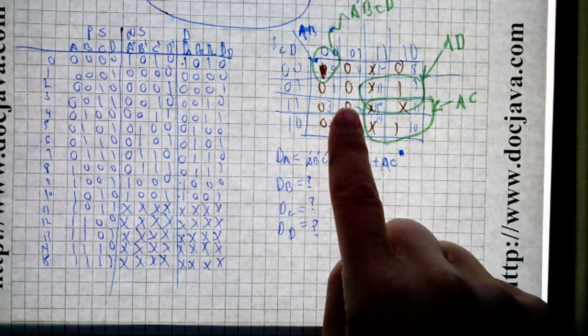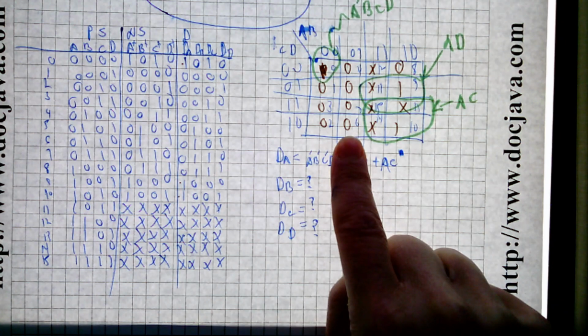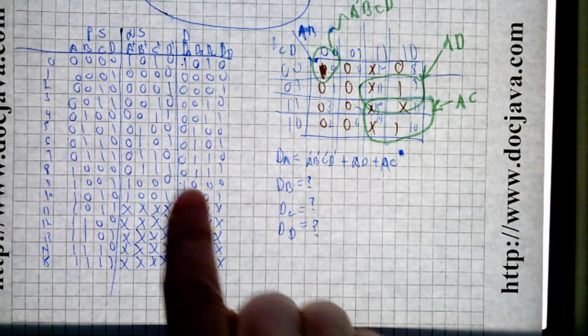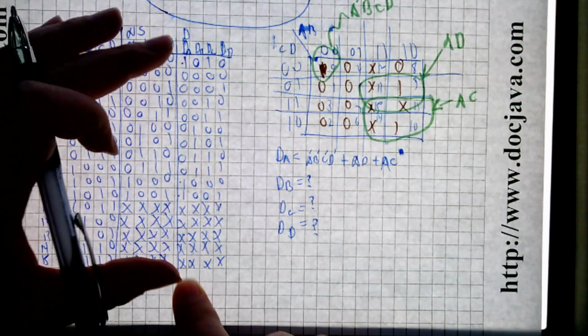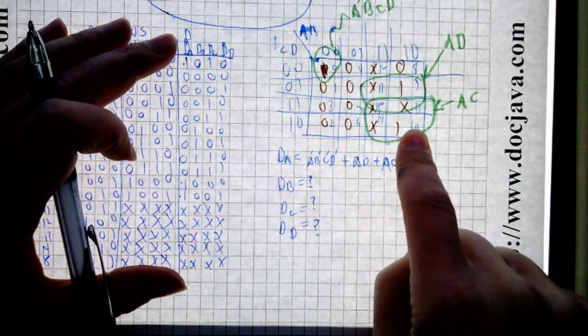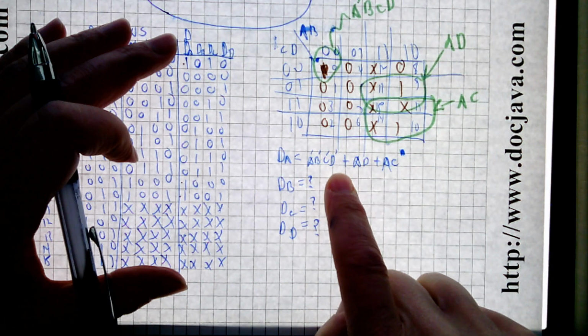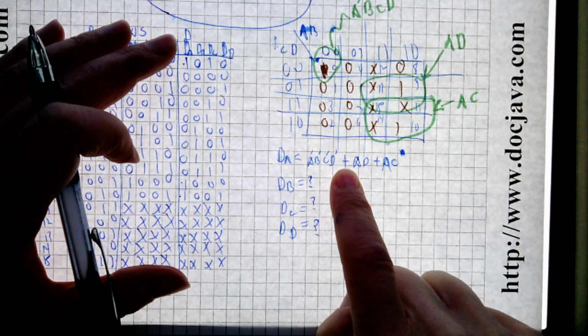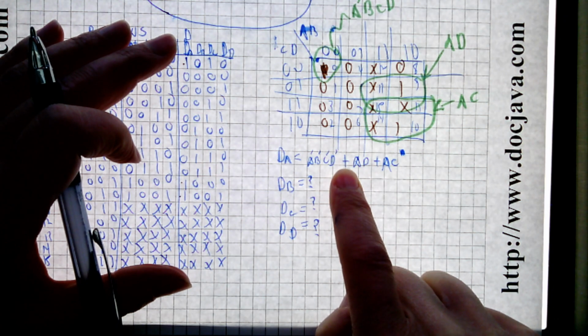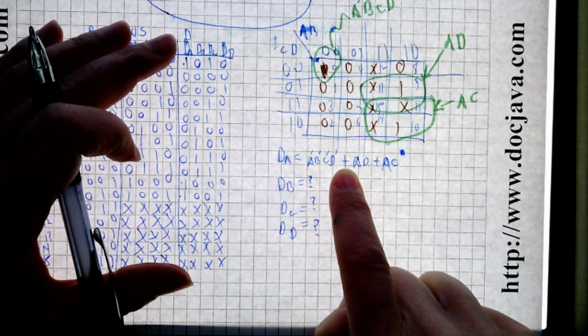Sure. So I filled out this K-map using the column through here. Once I knew the function for d sub a, and I filled out the column into the K-map, I did my looping to obtain the minimum sum of products form, which is needed for d sub a. That will be the foundation for the implementation of the combinational logic used to drive that bit of the counter.